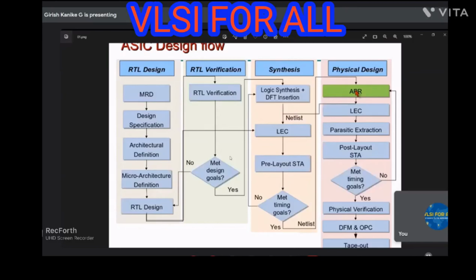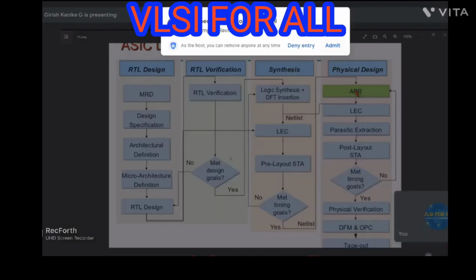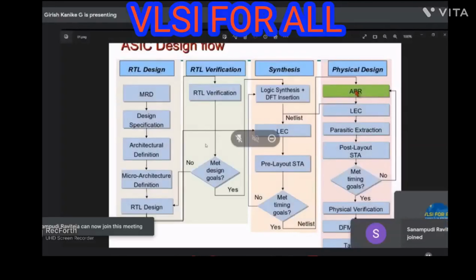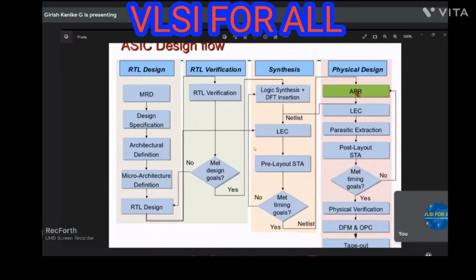So there's a timing analysis done. Just leave the static part, we'll come to it at a later stage. Just consider it as a timing analysis. Why do we need to do STA? Because in the MRD, whatever you have seen here, there will be a specific thing that this IC or this chip needs to perform some particular task in a particular time duration.